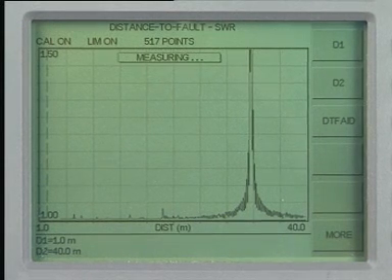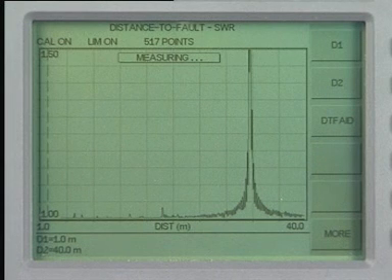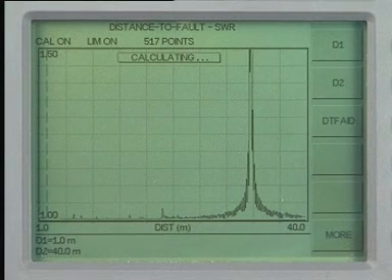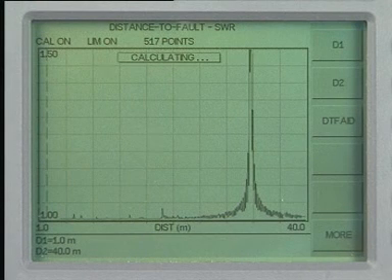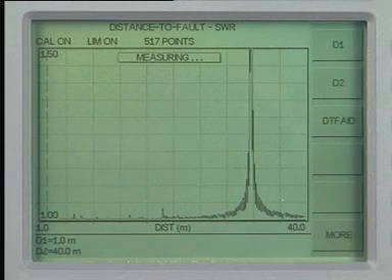In our example, we have a large VSWR disturbance at about 30 meters, which just happens to be the end of the cable. So now you know the location of the fault. It is just to inspect that part of the antenna system more closely to locate the fault.